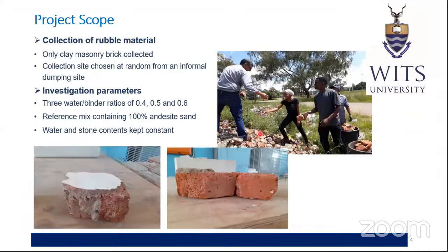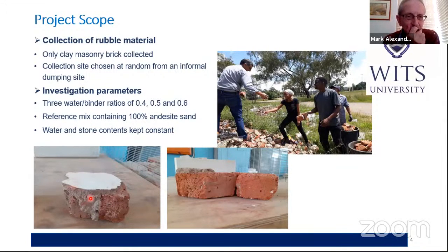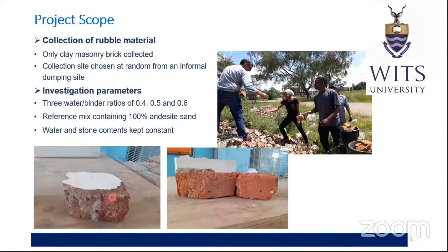As you can see, where I'm pointing with the laser, some of the bricks collected contain mortar, as well as paint that was left on the bricks. The investigation contained 3 water to binder ratios of 0.4, 0.5, and 0.6, with a reference mix containing 100% andesite sand, where the water and stone content were kept the same for the andesite concrete as well as the brick concrete.